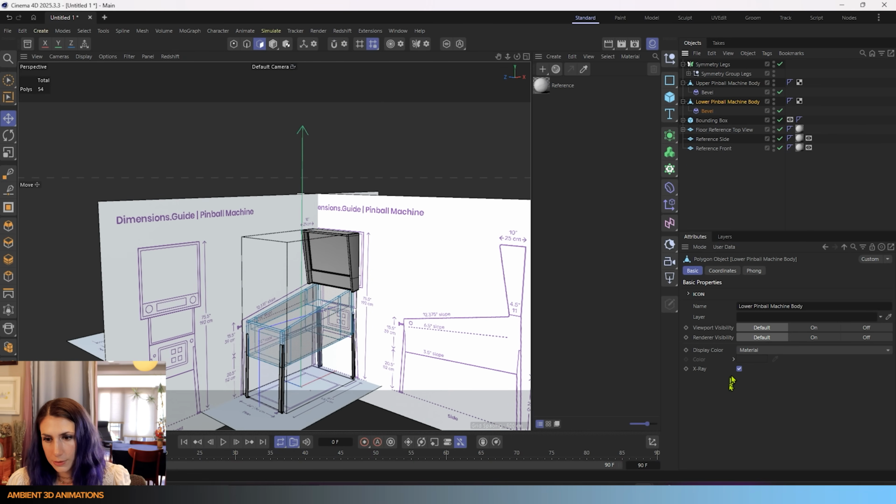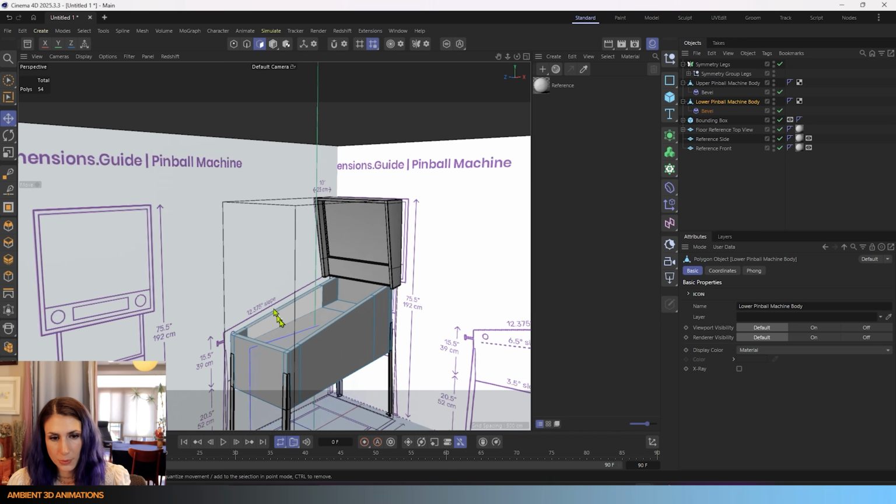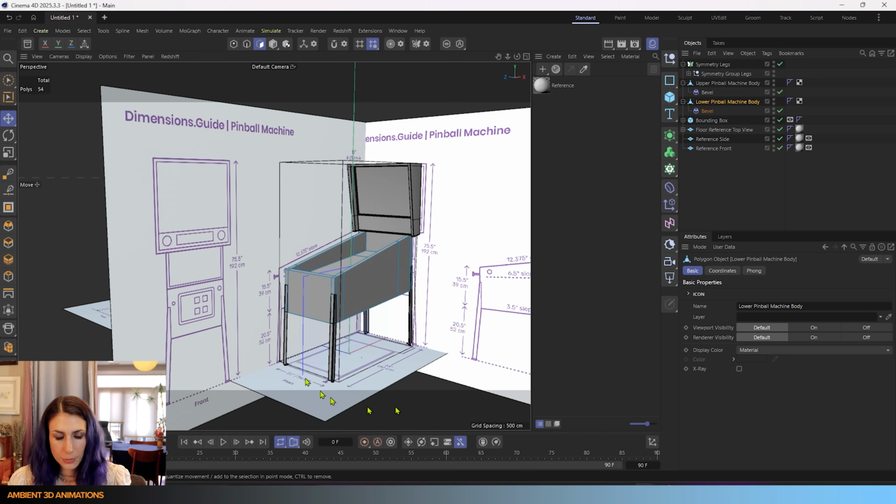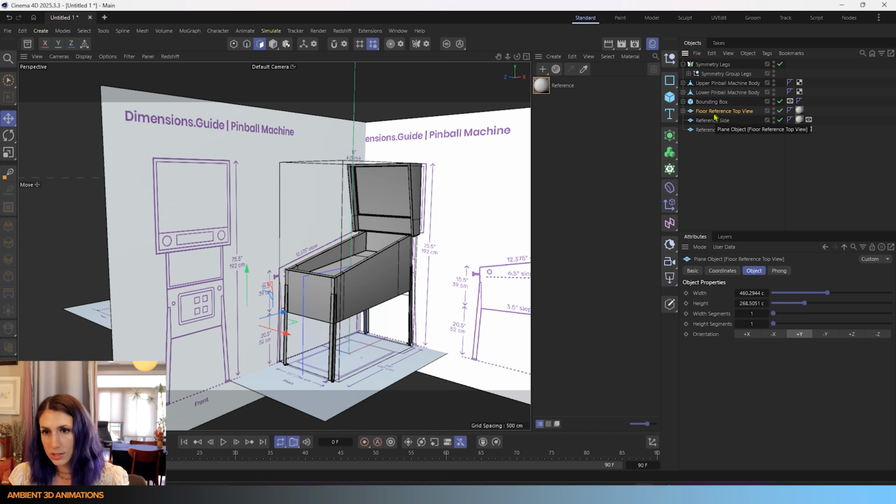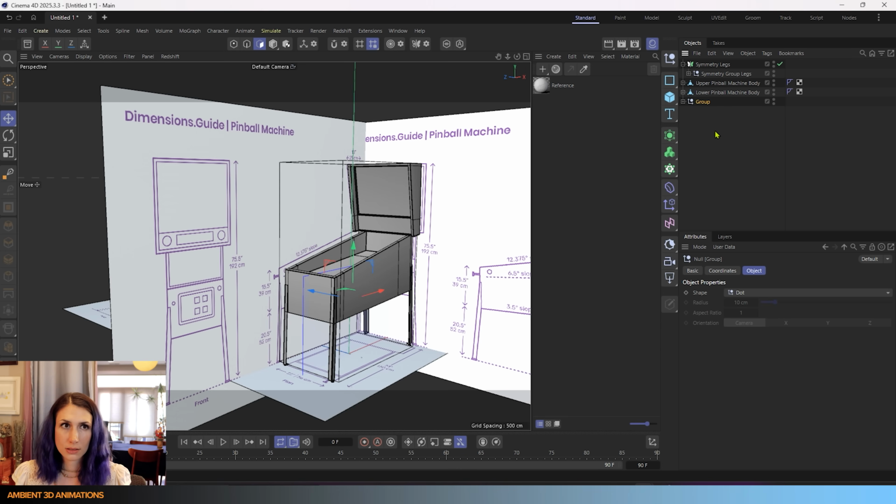And this looks good enough to put in a volume builder at this point. The proportions look good, the legs look good. I'm happy with this. I'm just going to organize things a little bit. I don't feel like we need our references anymore, but I'll keep them in our scene just in case. So I'm going to group all of these together using Alt-G. That's Option G on Mac, I believe. And we'll name this group References, just so that we have that going on in here.